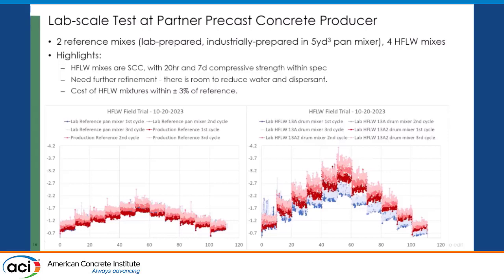So from that experimentation, all the high filler, low water mixes were SCC. 20-hour and 7-day compressive strength are within spec. We do need to further refine. We can cut more water and/or dispersant. It was a little too fluid. And the cost is within 3% now. It became a little narrower.